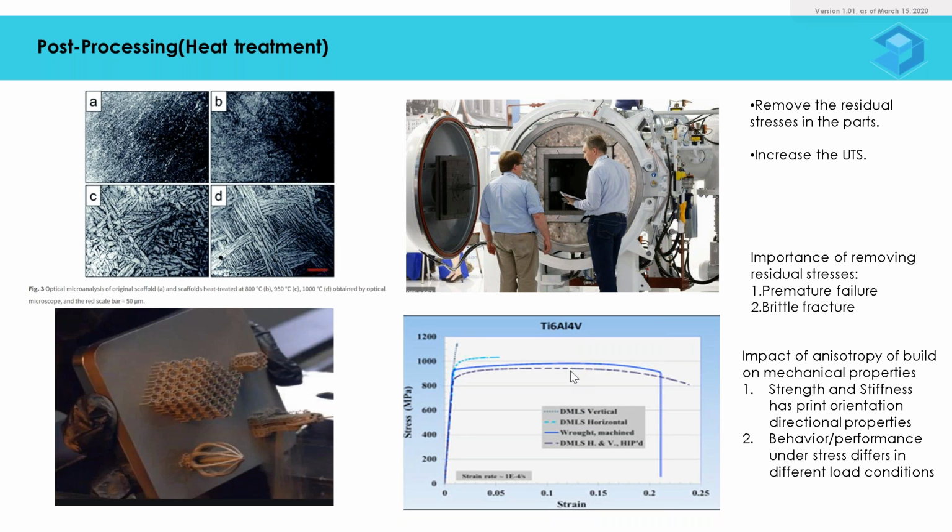As the 3D printing process dictates, it is layer upon layer, with very focused rapid heating and rapid cooling for phase change of the material. So that's the reason why the properties of the material are anisotropic, and there is an inbuilt residual stress because of the process, just like the welding process or something of that sort in case of metals. So we have to do that stress relieving cycle, and why is the stress relieving cycle essential?